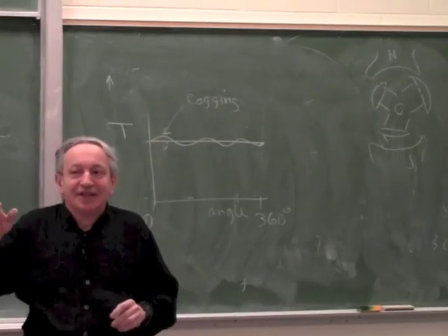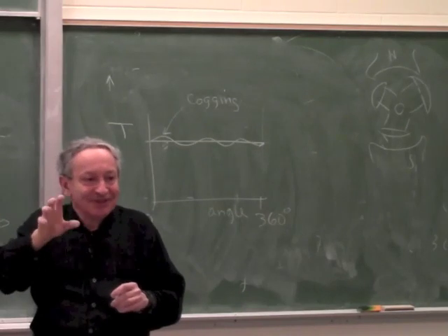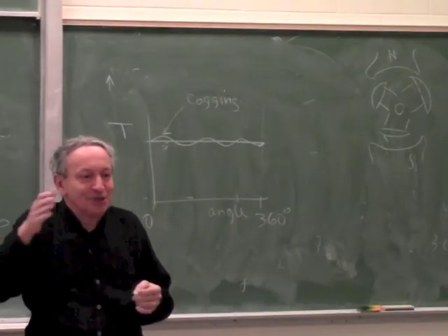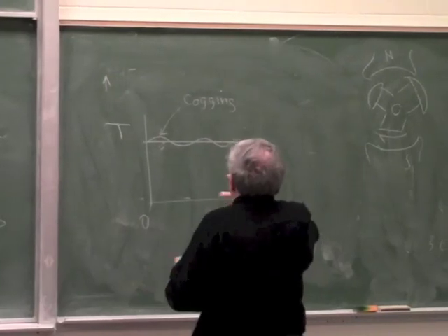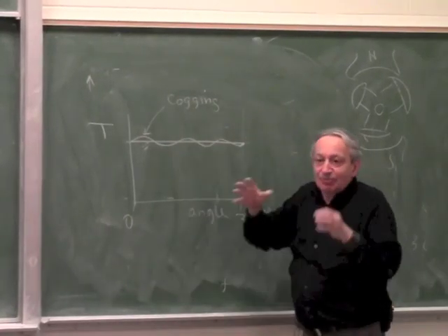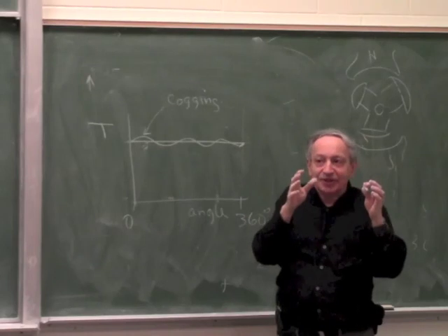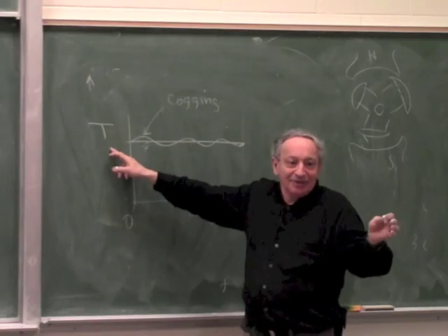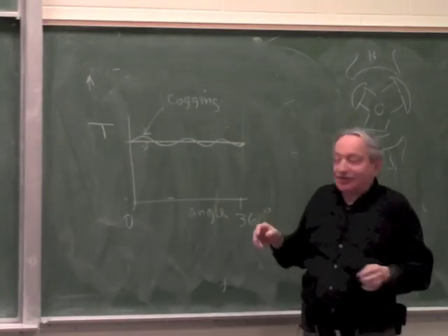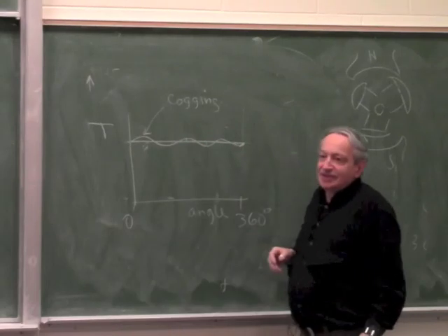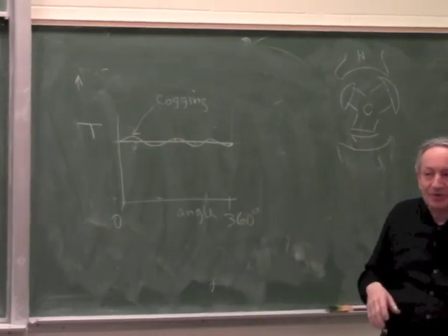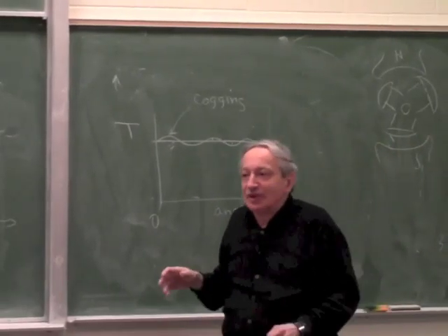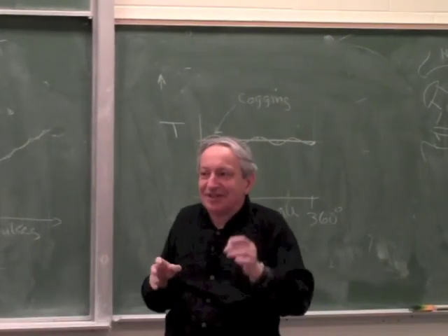But if the output depends on the position, it behaves as a nonlinearity, although it's still a linear system, but it's position dependent. If we draw the servo, and this was a block, the block called plant, or the block called actuator, it doesn't have a constant conversion, so many torque per amp. The conversion depends on position. So if this varies 10%, and that's typically what it is in a regular motor, it is the same as the gain fluctuating 10%, and that's not so good, because in some servos we like to make a perfect model and we need to know the exact gain.